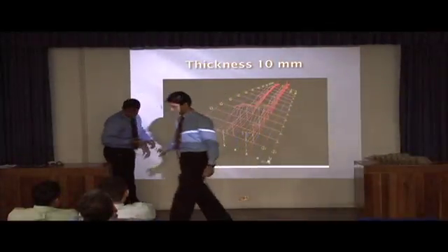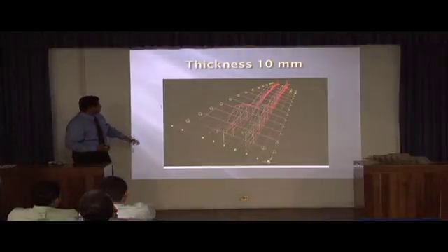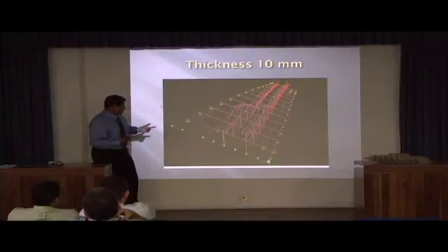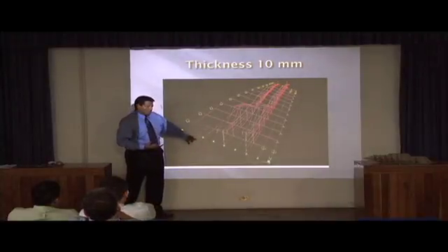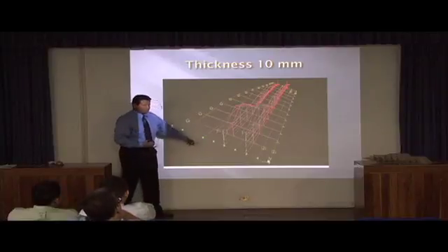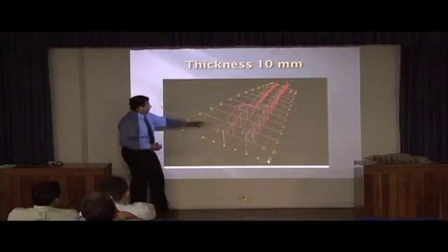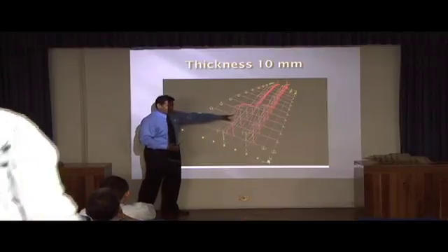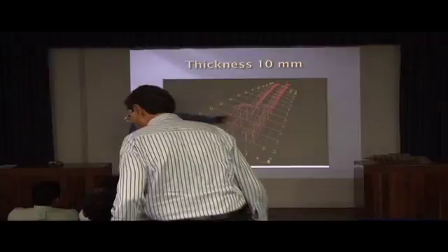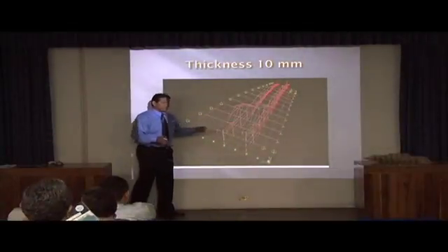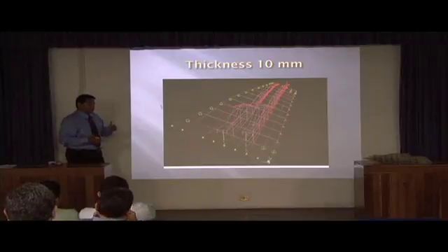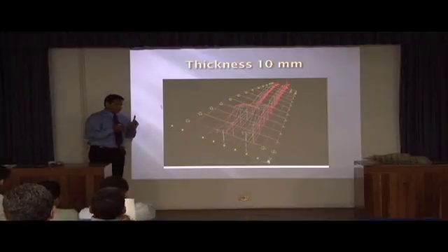We are going to analyze the same structure with an engine foundation thickness of 1 centimeter. For us, this is the worst condition, that is 1 centimeter, and 0.8 centimeter in the bottom plate. The gray lines are the undeformed shape, and the red lines are the deformed shape. Now with 1 centimeter is the greatest value, which I approximate at 0.5 centimeters, at least 5 millimeters. Next.